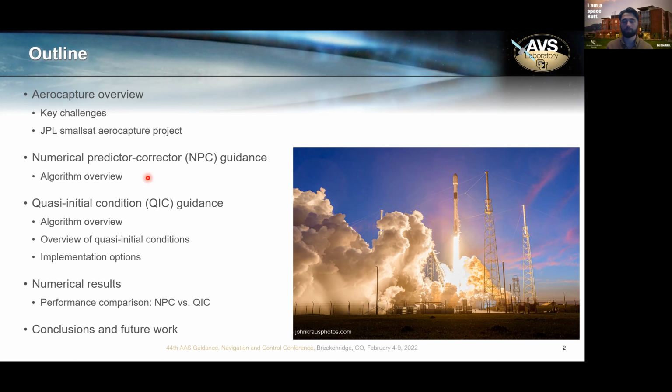It begins with the simulation calling guidance, which is active as long as the acceleration sensed by the IMU is greater than some threshold value. The guidance then propagates from the current navigated state to atmospheric exit, releasing that drag skirt at T sub j, the Jettison time, and then predicts the apoapsis error by simply taking that state at atmospheric exit, computing the apoapsis, and subtracting from that the target apoapsis. That provides an error, and we check if the error is less than some tolerance, and if it is not, the Jettison time is updated and this process repeats.